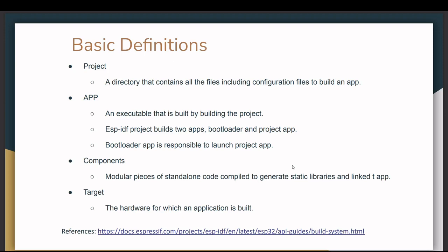ESP-IDF generates two apps. One is for the bootloader and another one is for the project app. The bootloader is basically the first thing that runs on the microcontroller after flashing, and then it launches the project app. Then we have different components in your code. These are modular pieces of code that are generated as static libraries and linked with the app.